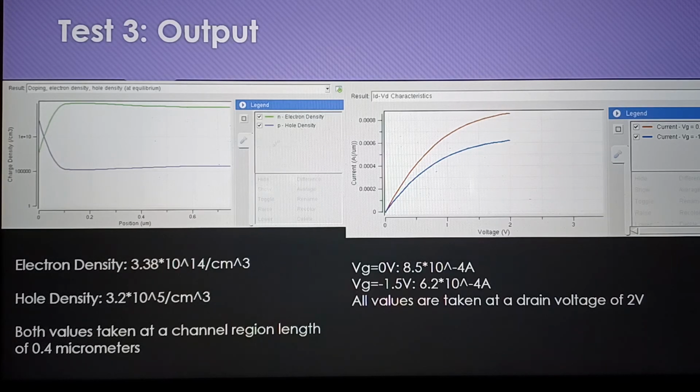So I'm getting similar differences of electron and hole densities that I got in the baseline and test 2, due to the changes of the doping level. But it seems that even changing the dimensions isn't decreasing the size, so I'm guessing changing levels of doping takes more priority than changing the dimensions of the device, and I also downscaled the device in this test rather than upscale, which I did in test one. So that is also a factor.